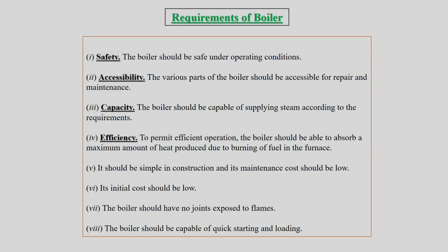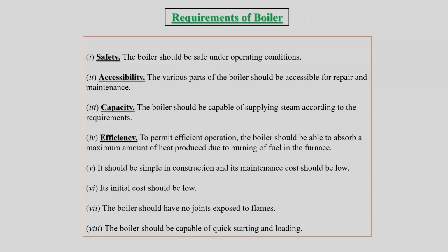Having said this, what are the requirements of a boiler? Basically, as I said, a boiler is a high pressure unit or a high pressure vessel. Since it is a high pressure unit, we first have to think about its safety, so its operation should be safe. Further, for maintenance it has to be accessible, all the parts should be accessible so that we can maintain and repair them. Capacity of the boiler is also important, since the boiler is supposed to produce steam at the desired capacity or desired steam rate and supply it to the turbine.